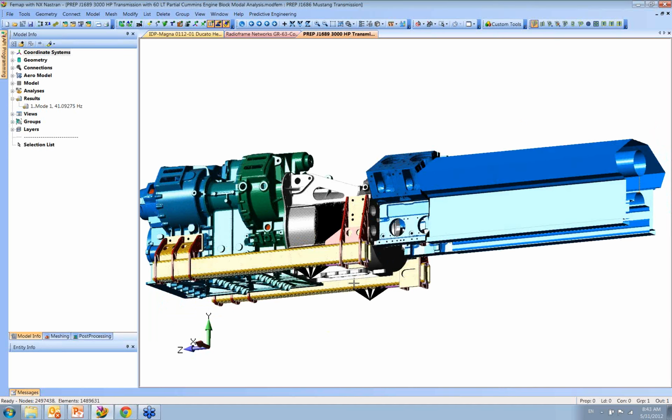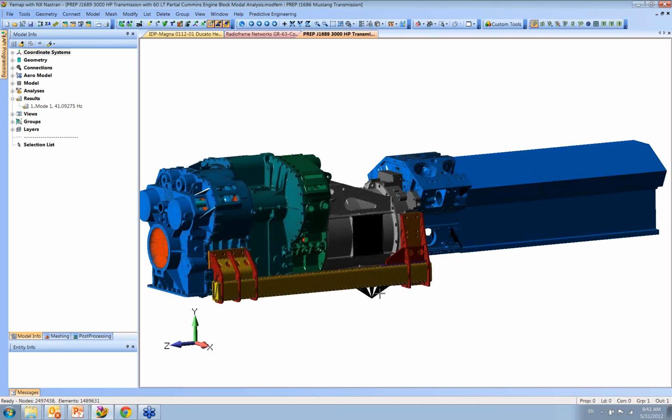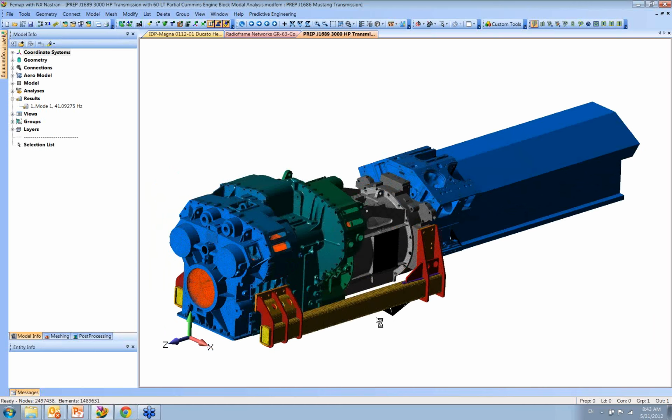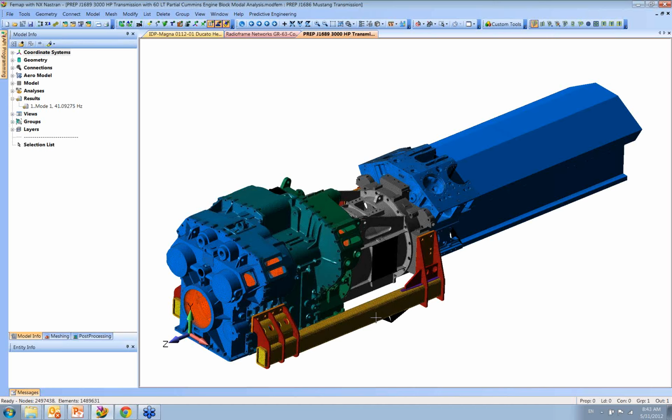The goal on this is that the engine spins at 1900 RPM, and so you want to avoid a frequency of 31 hertz. The rule in industry is that from your computer model, you want the first mode frequency 20% higher than the engine frequency. The reason they say 20 is because they don't trust the model. Typically, if they have dead-on data, they can say 10% higher than the first mode is good. But for modeling work, they want to see 20% higher.